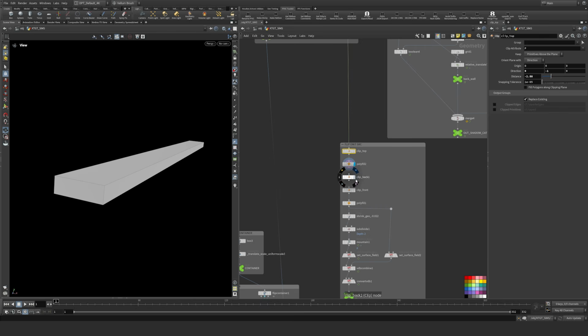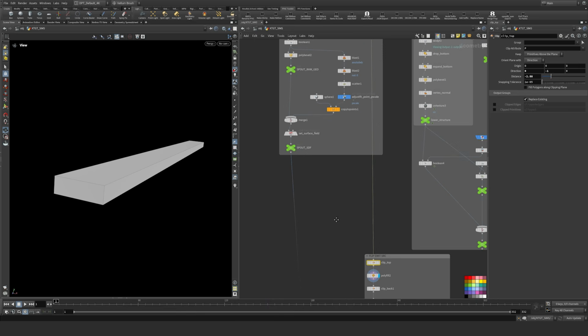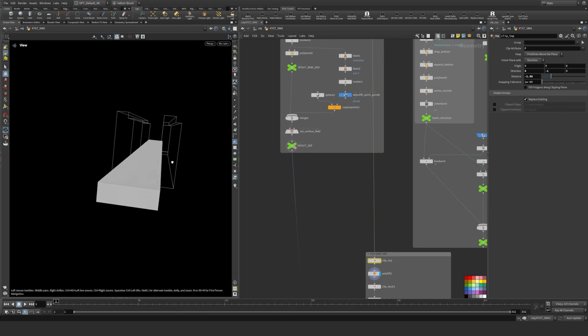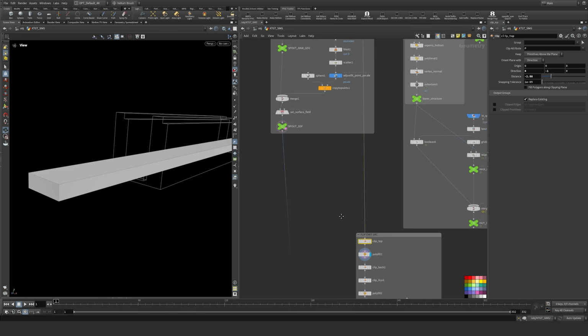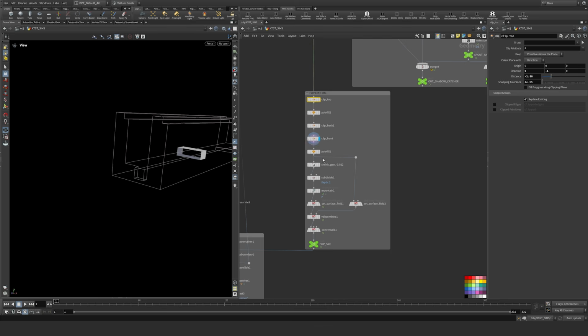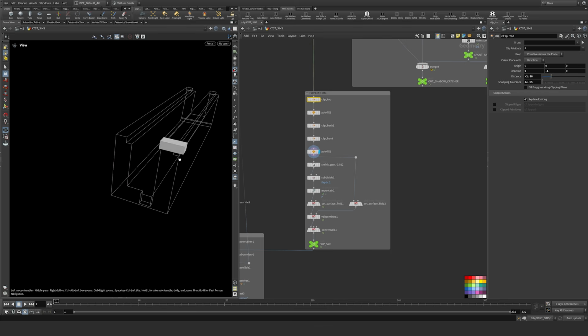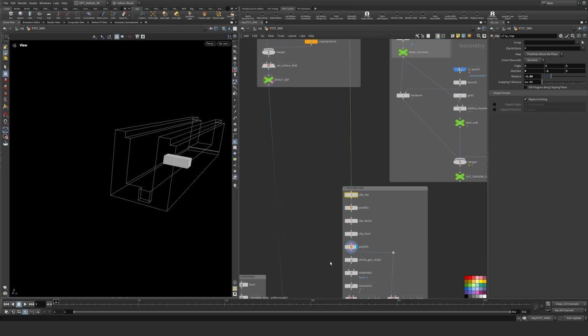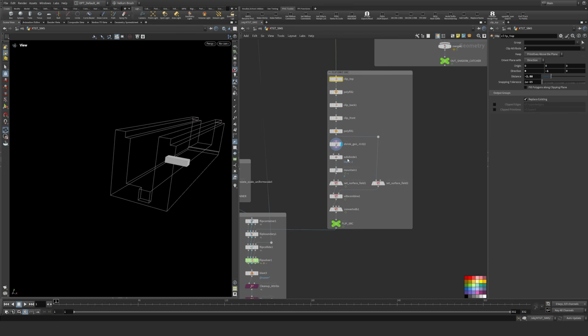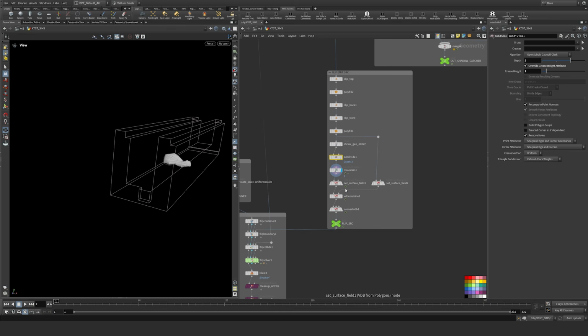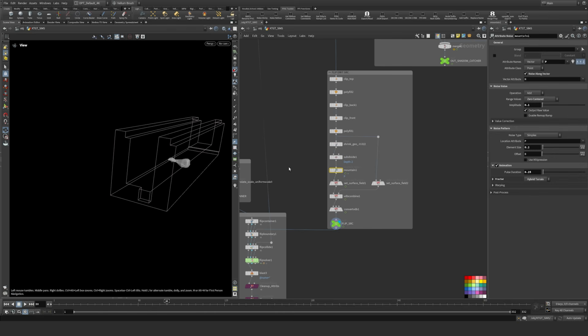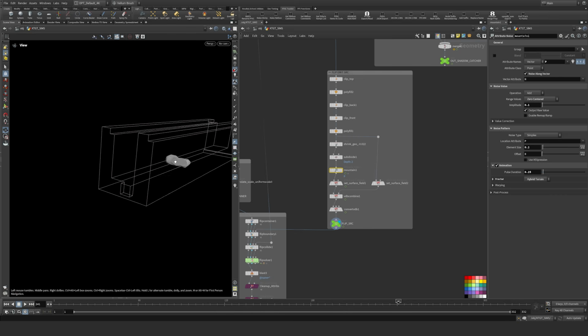So this is the interior of that channel. I'll even template this so you can see the alignment of that. Basically clip the front, the back, polyfilled it, and this is just keeping it procedural. That way, if I change one, this will update along with it. Shrunk the geo, threw a mountain on it, and subdivided it just to give us an interesting shape, and animated the mountain on that, just so it has some kind of movement, so that source varies every single frame.